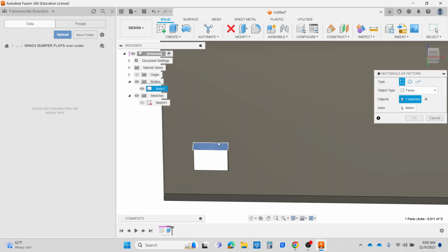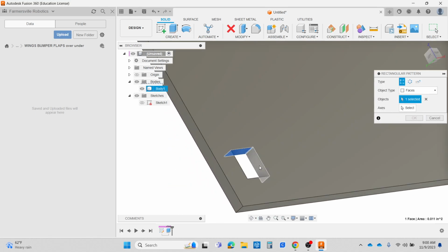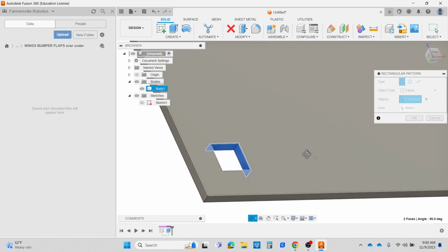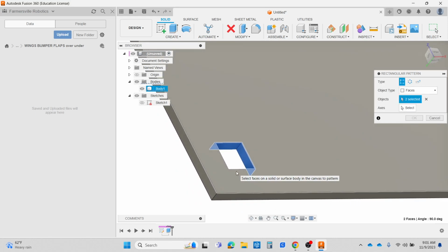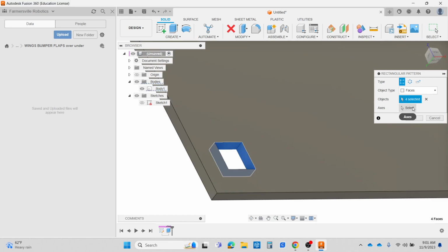If we were to use the hole tool, it would have been a feature, but we're going to grab these faces. So, shift and middle scroll wheel, and then I'm going to show you a through select. I'm going to left click and hold it, that way you understand how to do this, because I'm actually going through that face and selecting something. Okay, so I'm going to select this axis.